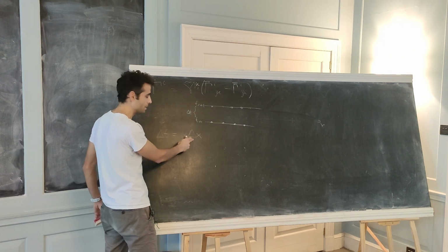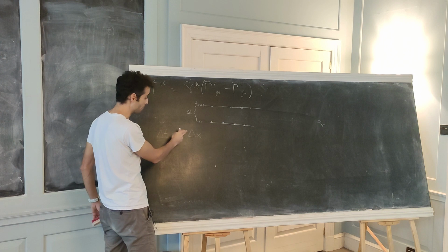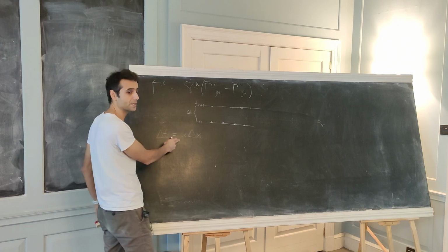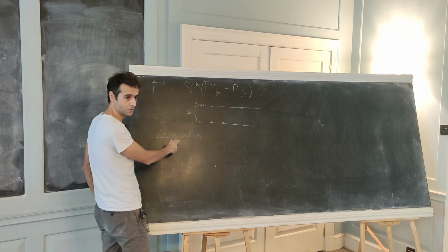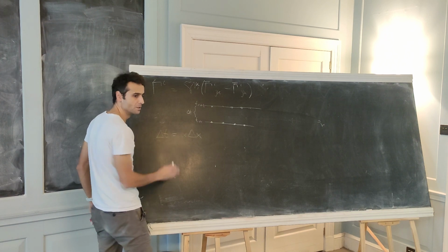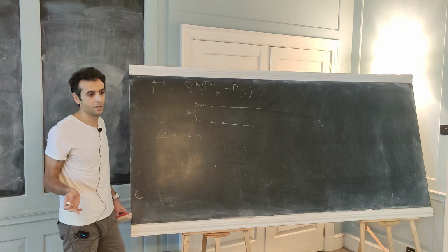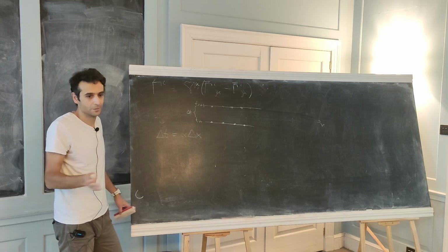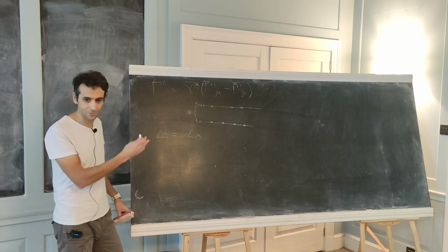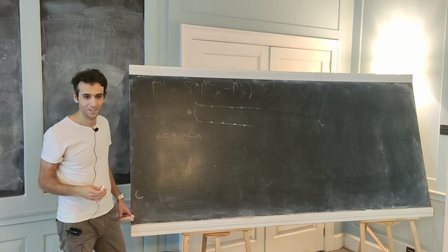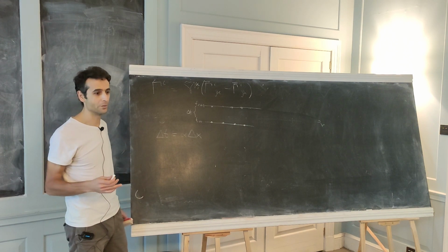So that's why you have this linear relation. In principle, for a given set of equations, you can choose the maximum value that gives you this causal connection. But in practice, what we do is just make it small, like 0.5 or 0.25, and if it works, then you are fine. If the code crashes, then that's one of the first parameters that you change. So let's make the CFL factor a bit small and see if it works.